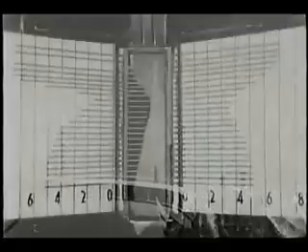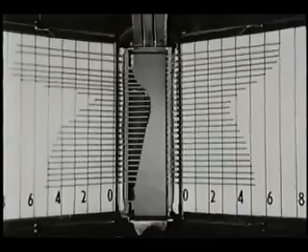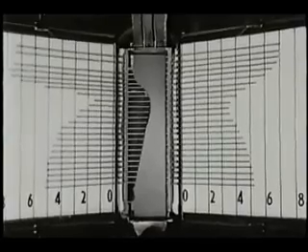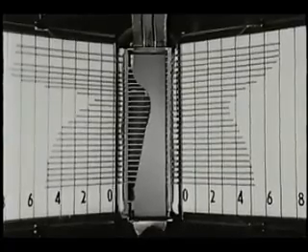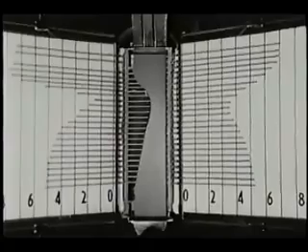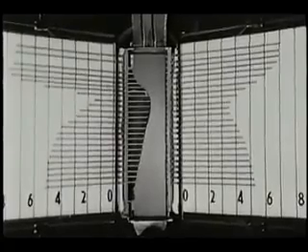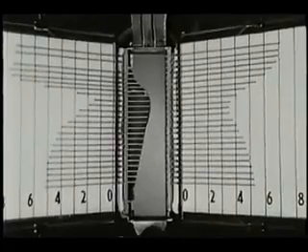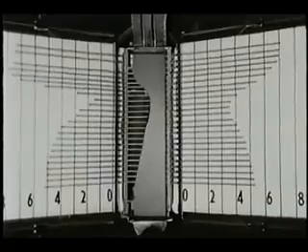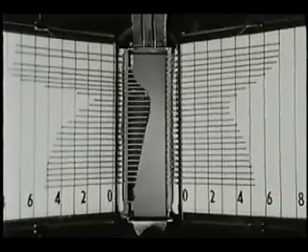The throat pressure at the curved wall is considerably less than at the straight wall because of the streamline curvature. When we use venturis for flow measurement, the pressure we measure at the wall is therefore not the average pressure at the throat. That is one reason for calibrating venturi meters.